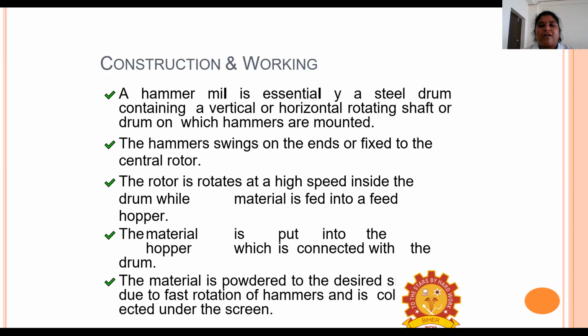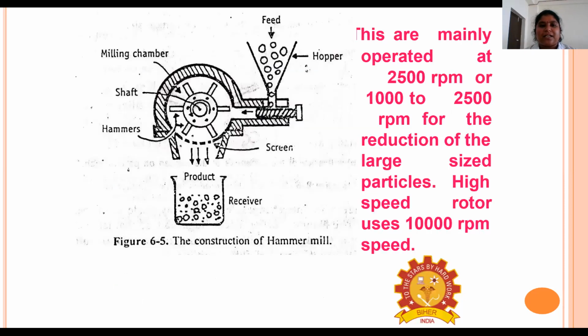The material then hits the hammer ends, and the particle size is reduced to the desired size because of the impact mechanism, and it is collected in the collector.